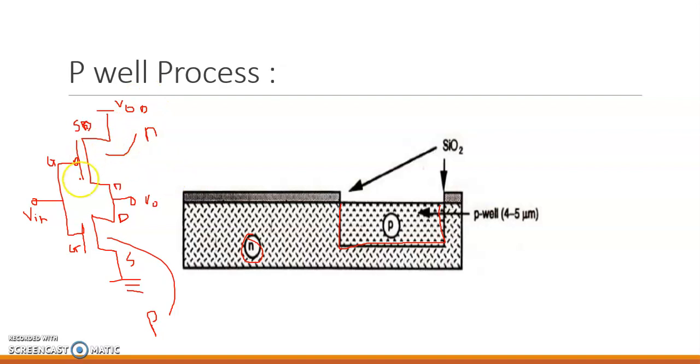In order to form a CMOS circuit, as we know, some of the connections are permanent, like the gates of both the transistors are shorted, right? So that can be connected internally only. This can be done while doing the fabrication only. So for that I should know the circuit and I have to use a proper mask to make the connection.